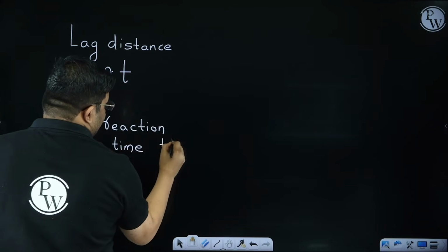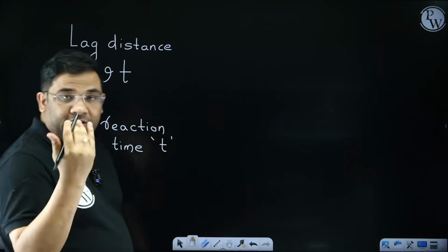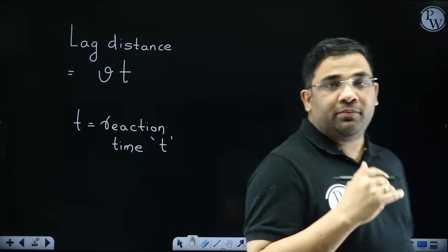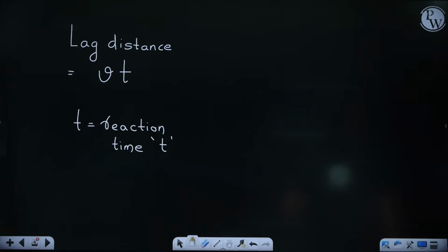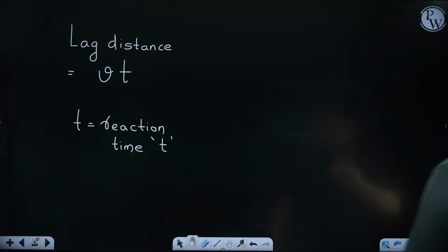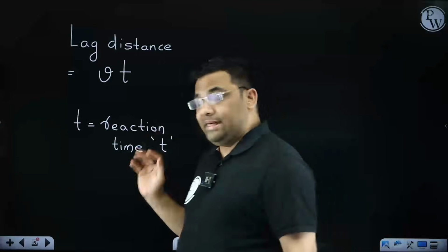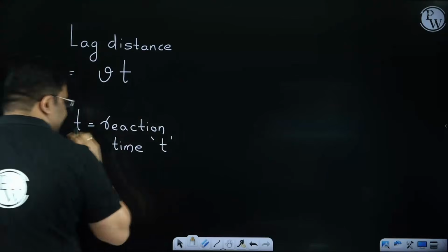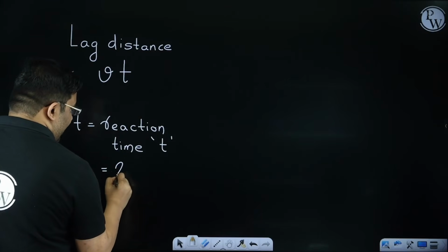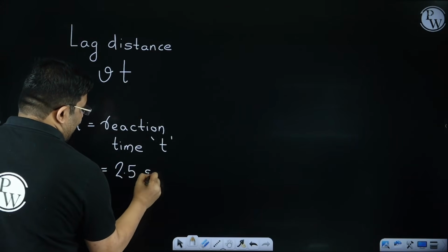Now the reaction time t will be different for different drivers, but there has to be a standard value. So the Indian Roads Congress, IRC, recommends that this reaction time t should be equal to 2.5 seconds.